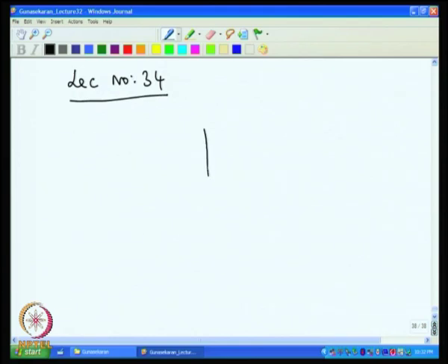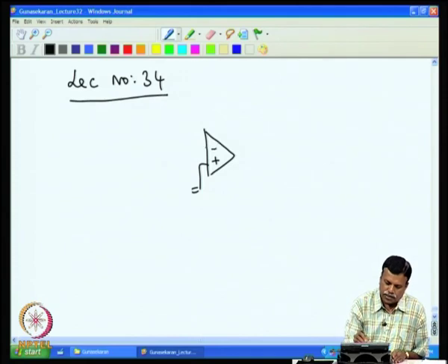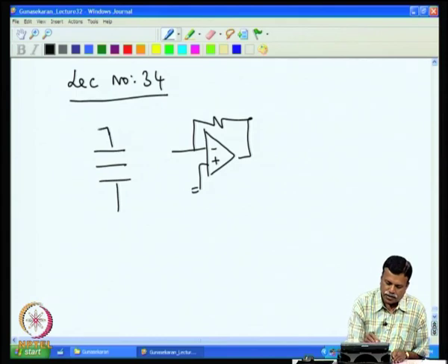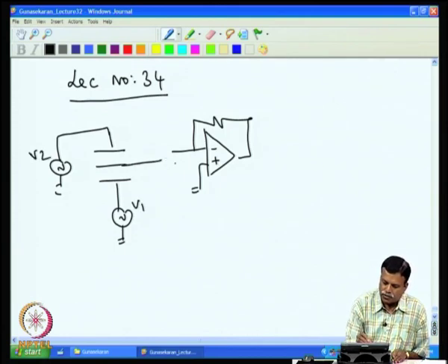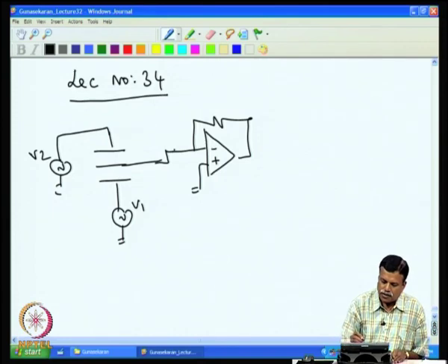There we discussed that if we use a non-inverting amplifier for capacitance measurement, we connect the resistance here, and then we showed that we can put 3 plates, with a source here X and then another source, V1 and V2, and then we can connect to this. This is actually useful for space variation.